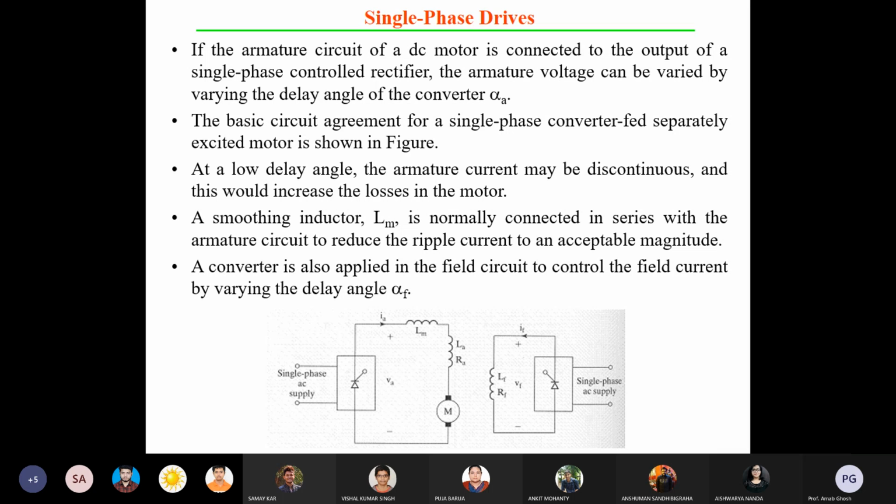Either on or off. What benefits are there? Power is P equal to V into I. If either component is zero, the power, that is the switching or conduction loss, will be zero. Switch on means current is flowing and voltage is zero.